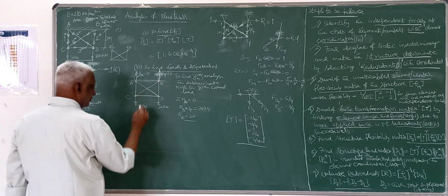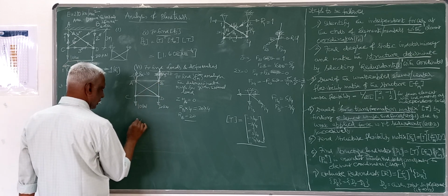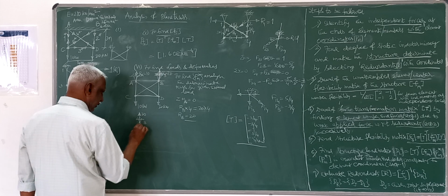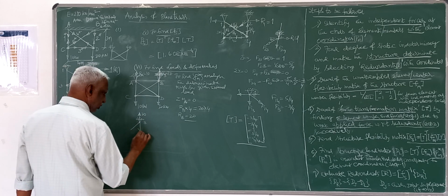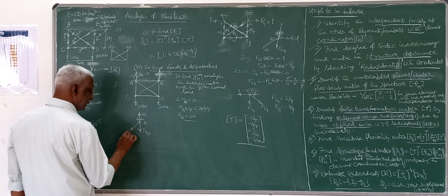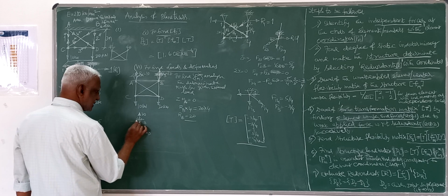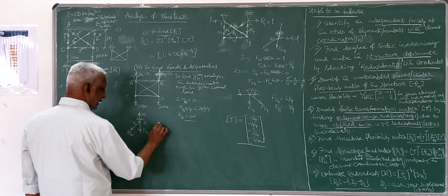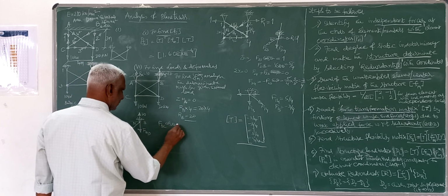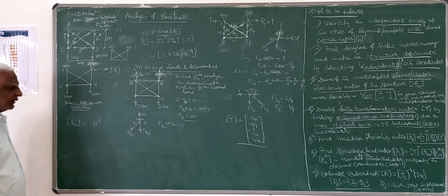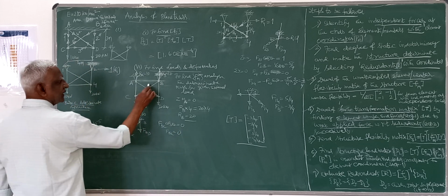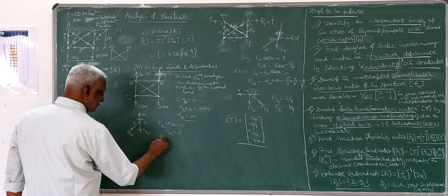So now you take the free body diagram of support B. You have 20 and you have these members. The force in this member BD, I will take it as FBD, and similarly the force FBC, if I take theta, then FBC cos theta is equal to 0. So therefore this FBC, the force in this member BC, is 0.